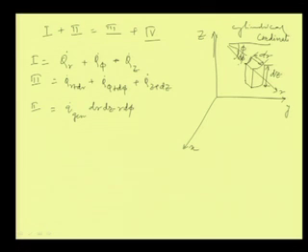Okay. Now, your 4th term is again the accumulation term, or the rate of change of internal energy. In the 4th term, it should be rho Cp into dr dz into r d phi into del T by del t. Again here, what we are doing is, we are not assuming anything, we are calculating T as a function of coordinates as well as time.